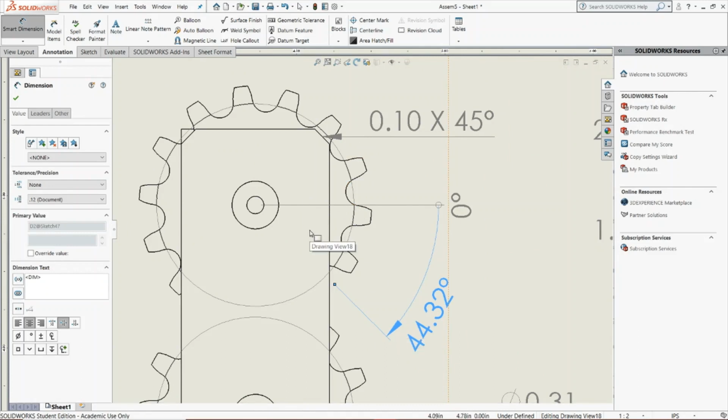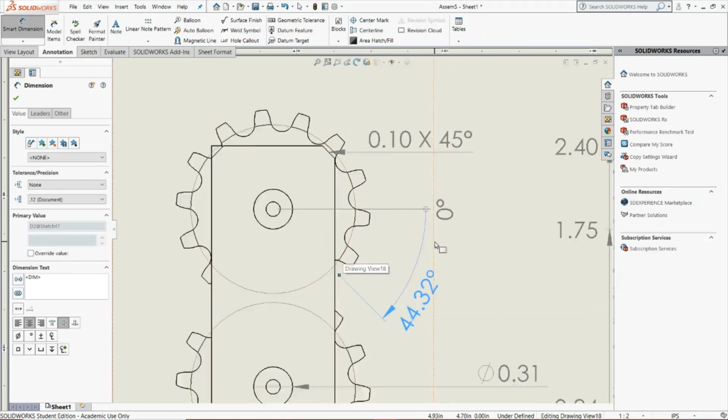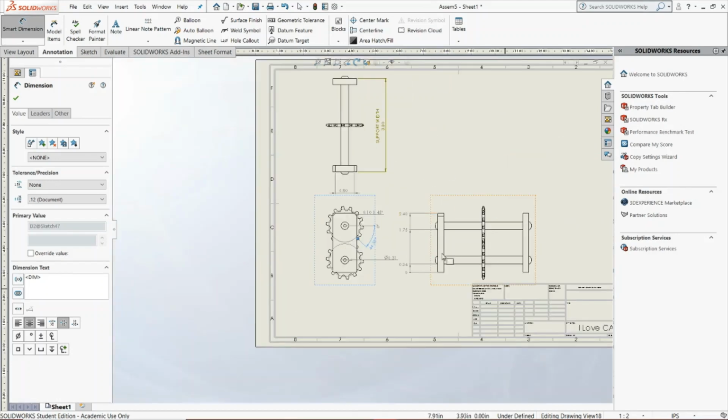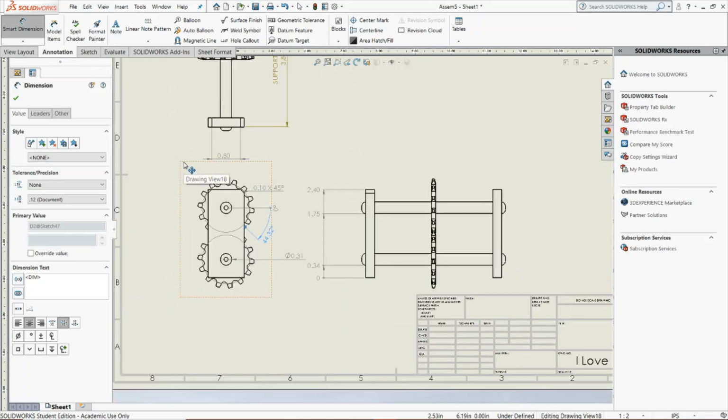Again, this is something that comes up frequently if you're in shaft design, but other than that, I wouldn't necessarily be too concerned about it. Just know that you can click vertical edges with it, and it'll tell you the radii, or the amount of the angular distance that particular feature spans. It's almost like the ordinate system, but in its angular counterpart.